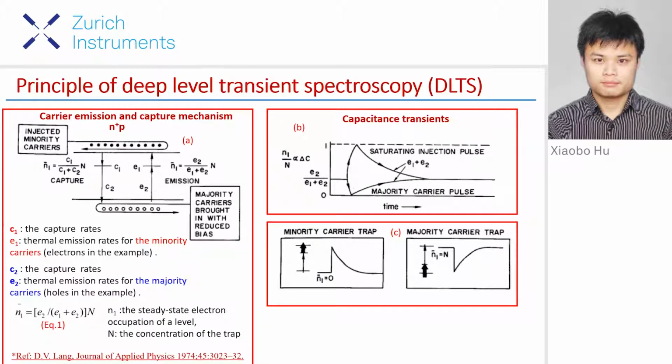This technique is used to obtain information about an impurity level in the depletion region of a Schottky barrier or PN junction by observing the capacitance transient associated with the return to thermal equilibrium of the occupation of the level following an initial non-equilibrium condition.